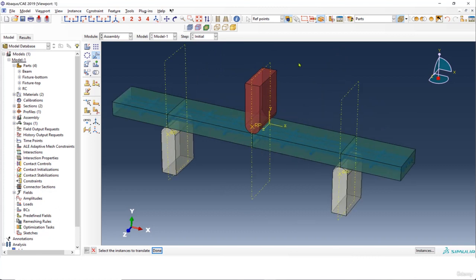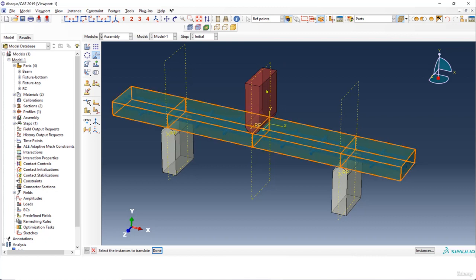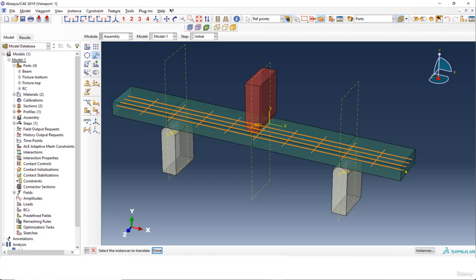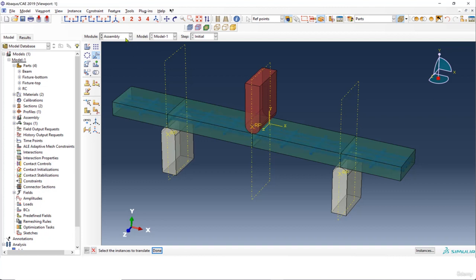So currently Abaqus actually doesn't know that your beam is reinforced. I know that you put the reinforcement in the middle of the beam, but if you have direct force, Abaqus doesn't really know that you put this one in the middle, and probably you're going to get a convergence problem. So how are we going to solve this? We're going to solve this in the interaction section, but before doing the interaction, I'm going to create a step.